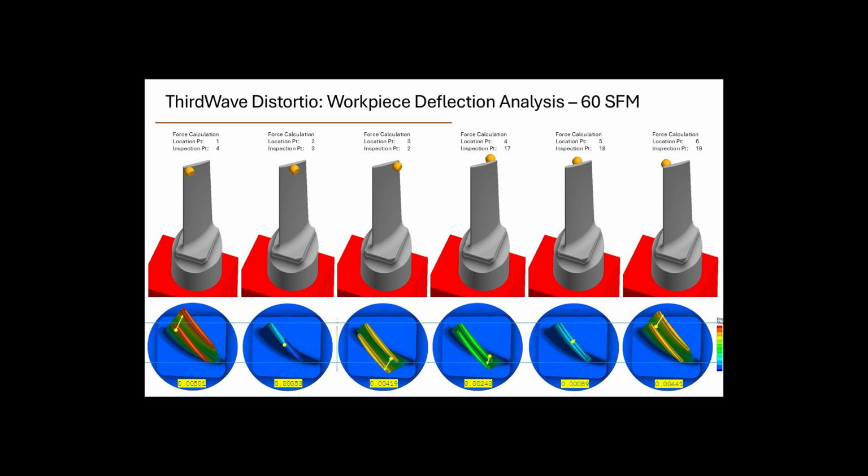So here at control point 1, we're deviating by 5 thousandths. You can see here it's about 5 tenths in the middle, and so on and so forth. So it's a significant deviation. 5 thousandths is quite a bit.